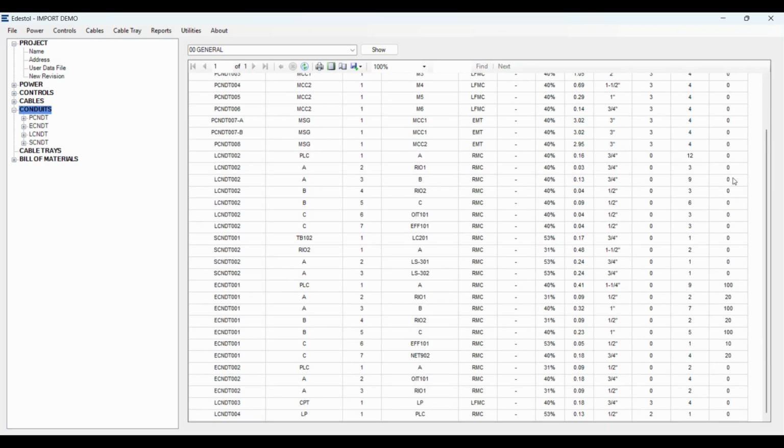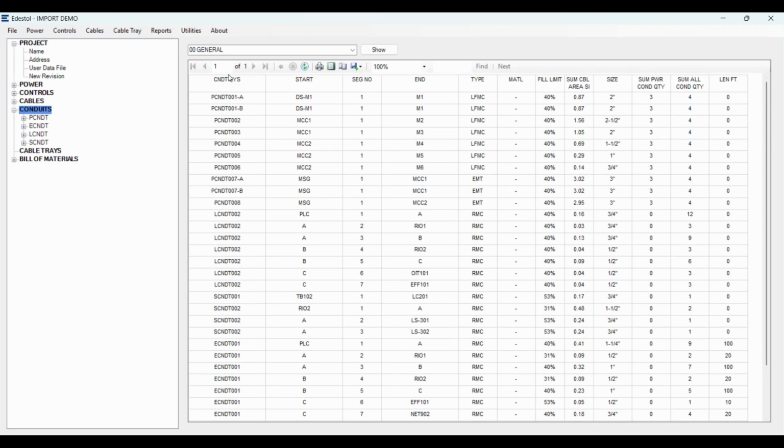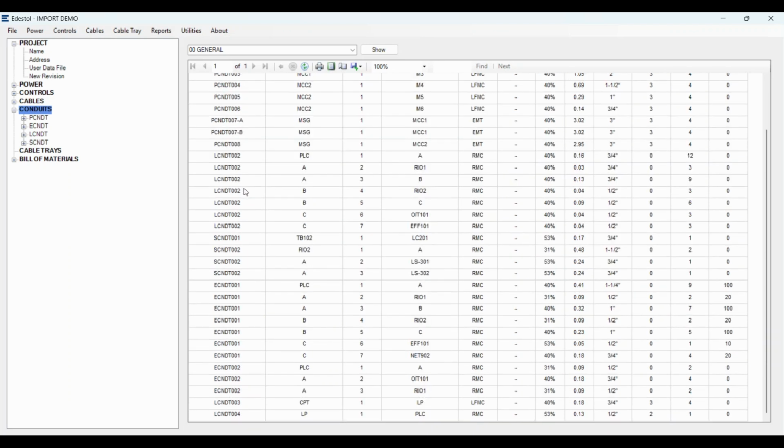And you can see we filled in up here length feet. This is your actual raceway, complete raceway schedule of every conduit for power, for low voltage power, for signals, for Ethernet, your communications, and then some low voltage down here. So you can see we did some e-conduit segments, 120, 120, 100. And then basically these are your conduit systems.